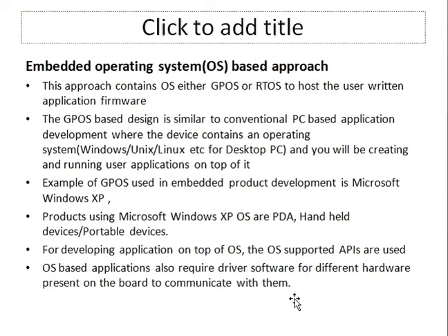So why is a device driver required? If you have a hardware unit present in your embedded product, and that hardware unit needs to be connected or interfaced with the help of an operating system, you might have an operating system like Windows 8.1 Embedded for embedded applications. In that case, if I want to drive a device, if I want a peripheral to be enabled with the help of the operating system, then you require device driver software.